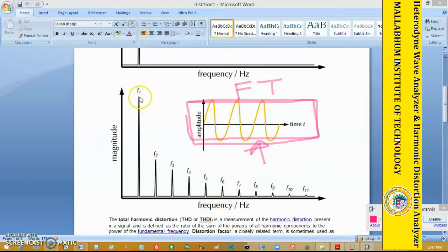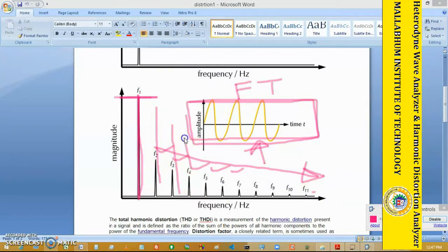So this is the fundamental frequency f1. You can see that this is the fundamental frequency, which has the highest amplitude, obviously. And next are f2, f3, f4, f5, f6 with diminishing amplitude. That means these are all the distortion. If the distortion component is higher like that, then you don't get the original sound. The original sound is totally suppressed by these harmonics. These harmonics are undesirable, but they are inherently produced in the circuit due to the different circuit components. This cannot be avoided totally.